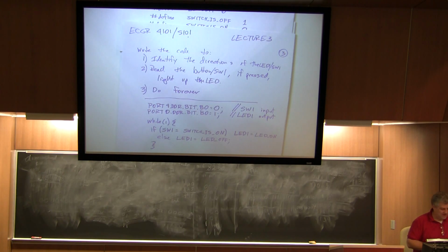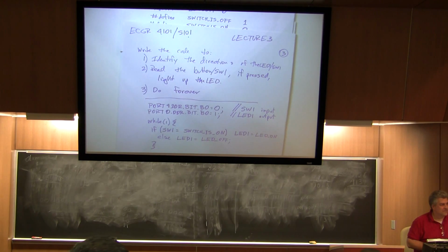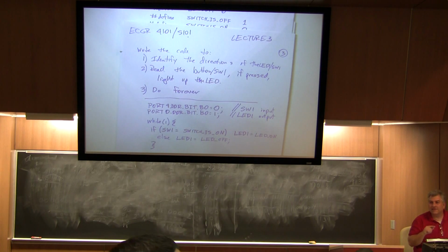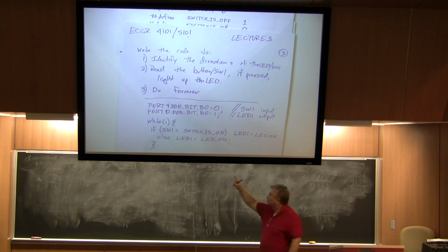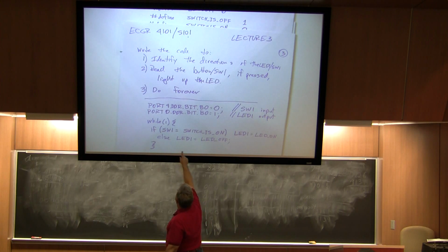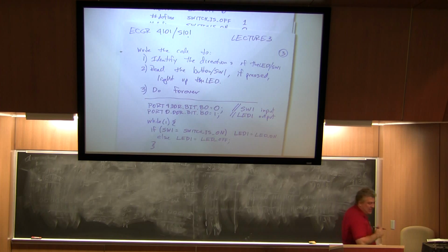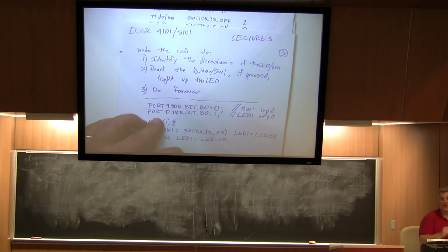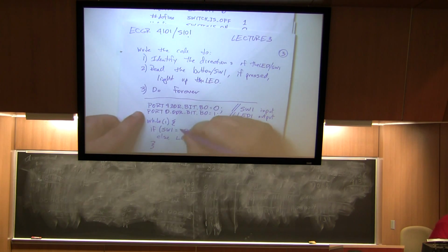All right, so what do you have? It's exactly the same thing except I use the pound defines, all right? Is there an error in this? Yes. Okay, what is the error? Notice this comparison. Switch 1 is assigned to switches on. So what you really need to have is, notice I have an extra space in there.